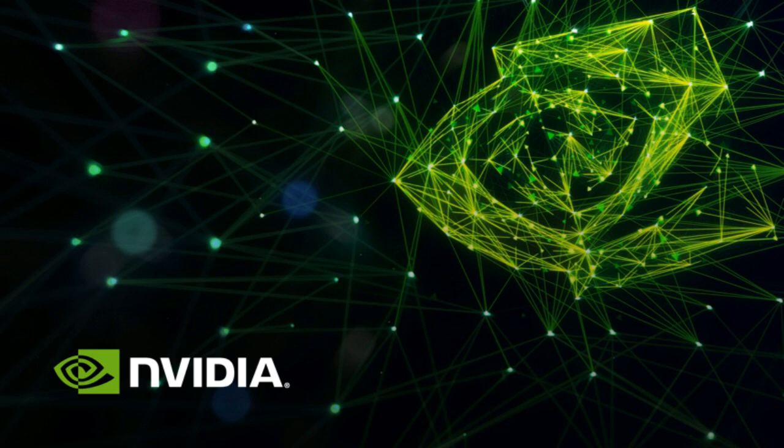They actually make AArch64 builds. AArch64 is the architecture of these ARM 64-bit boards. Like x86 has a different build architecture than AArch64. So if you have a closed source SDK, like a lot of these GigE Vision SDKs are, you need to ask them to either provide it or download it from their website, like Point Grey has one. Or, there are some open source Linux projects out there that do support GigE Vision that you can just compile, and some of them even have GStreamer plugins too.